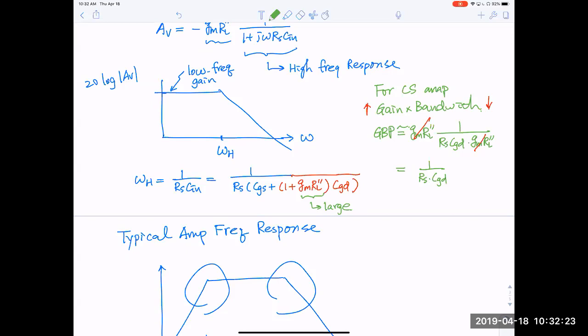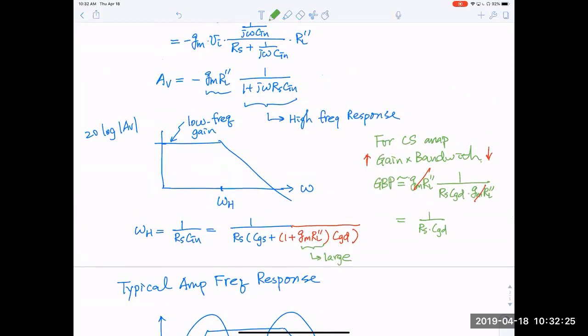If you recall our discussions before, if you increase your gain, we basically stay on this line, the same gain bandwidth product, and you arrive at a higher DC gain. This line means you are moving with the constant product behavior. You can go to higher gain, but the frequency response is lower.